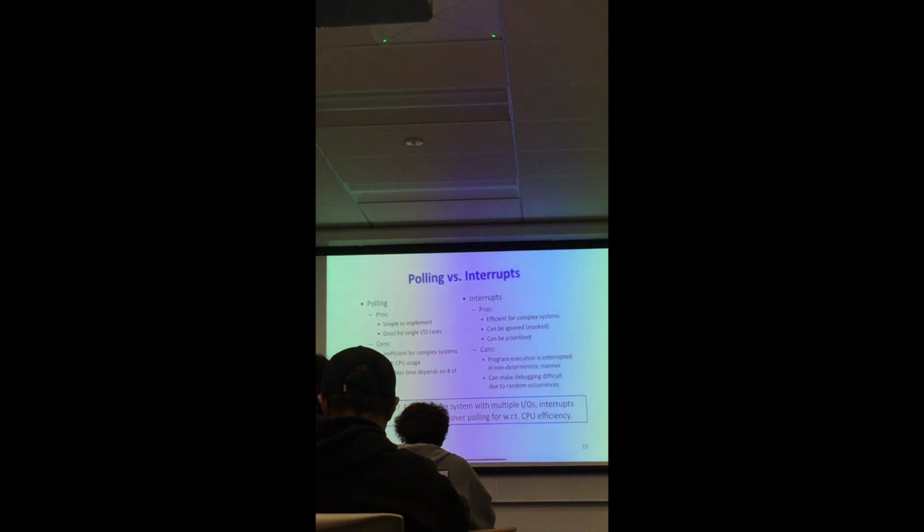Interrupts don't need it, because once an interrupt is generated, the CPU will know which one actually wanted that attention. But there are also advantages and disadvantages in these two processes. Polling requires a permanent process of asking devices for attention if they need attention. Interrupts, on the other hand, have overhead with the CPU storing information from registers in the stack. So it is always a trade-off.